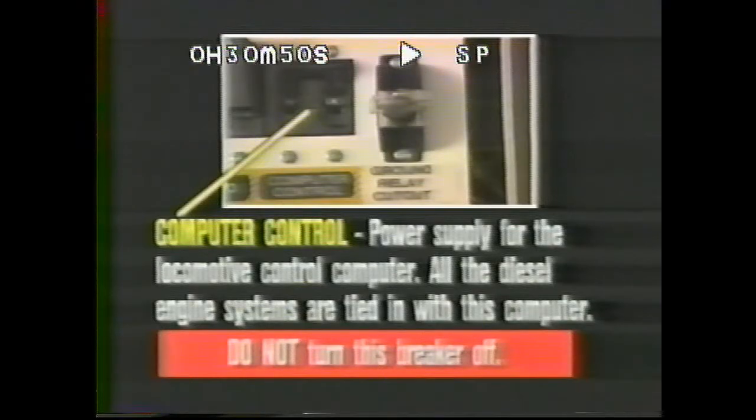Computer control. Power supply for the locomotive control computer. All the diesel engine systems are tied in with this computer. Do not turn this breaker off. Ground relay cutout switch. Disables ground relay protection on the locomotive. Only authorized maintenance personnel may operate this switch when performing tests. Parking brake. Power supply for the electric parking brake.